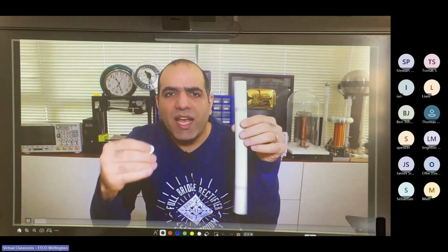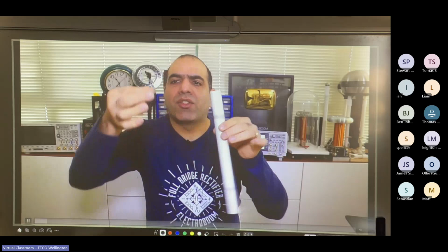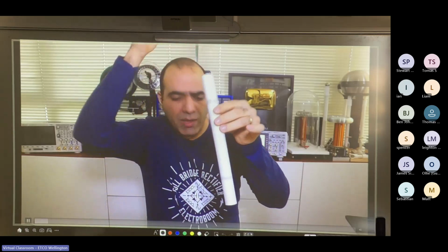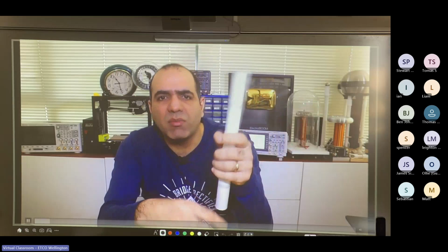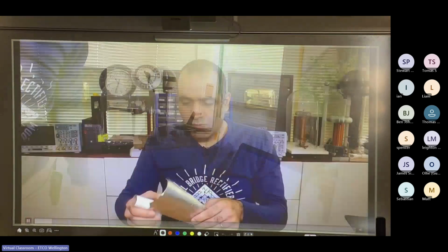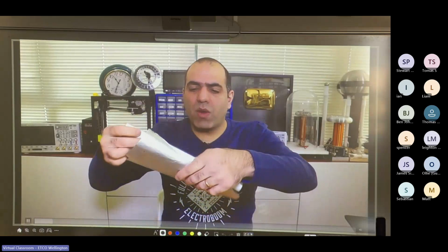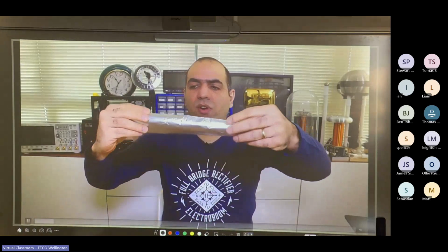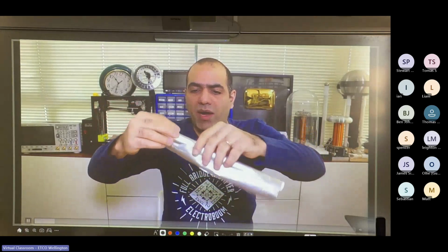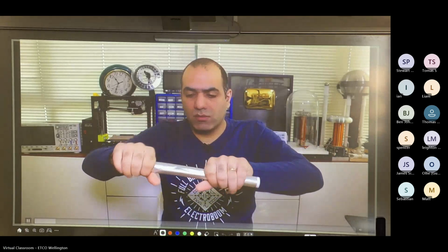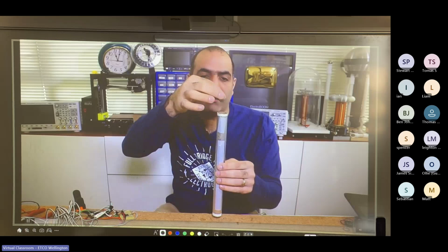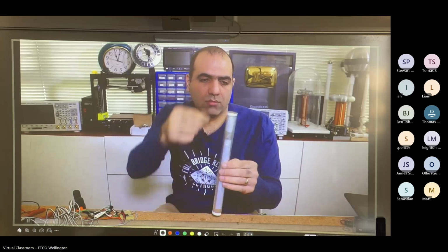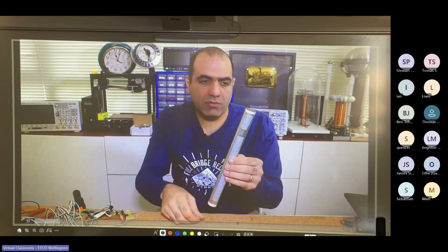What you have probably seen as an effect of eddy current is that throwing a magnet through a copper pipe slows the magnet down. This is paper though. I didn't bother buying a copper pipe just to add it to my collection of unused pipes here. I'm pretty sure it's easy to make one at home though. All I need is aluminum foil I wrap around my paper pipe and tape it. Now my magnet drops through air at this rate and through the pipe, the exact same rate.